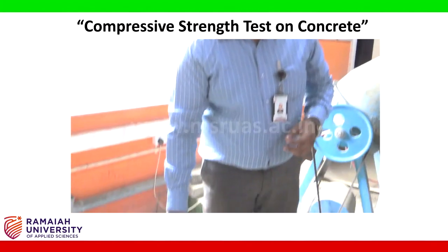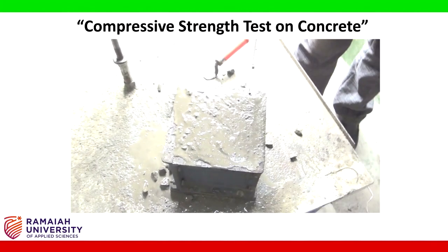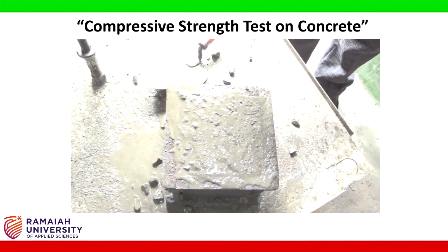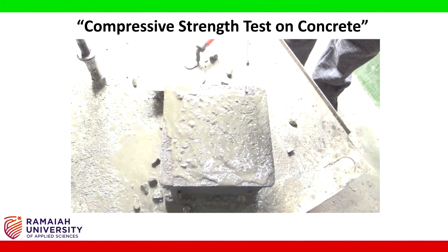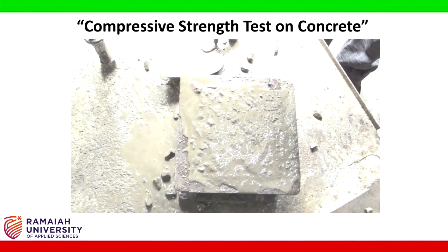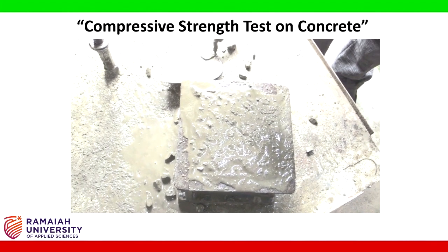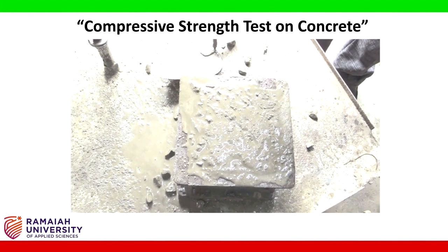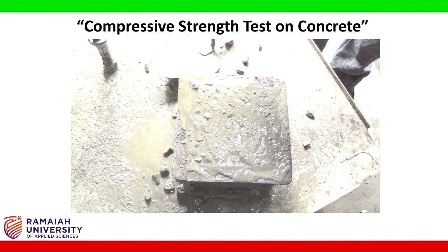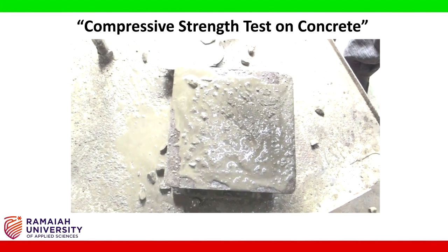Like this, the cube is prepared. So here we are doing only one sample. As per the IS requirements, a minimum of 6 samples has to be cast for one particular test. Right now I am doing only one sample.